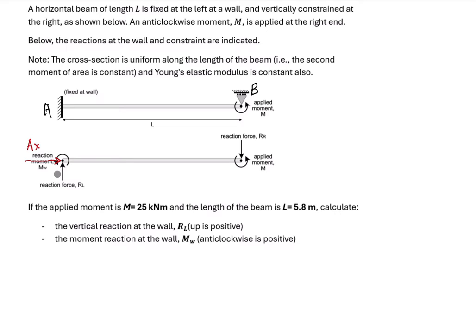In this question they didn't put AX on the free body diagram. Here is the reason. If we write down the equation of equilibrium in the x direction, sum of Fx equals 0, we find there's only one force in the horizontal direction, that is AX, so AX equals 0. So in this question AX is not put on the free body diagram. We can just delete this force because it's 0. We can also write down two other equations of equilibrium.